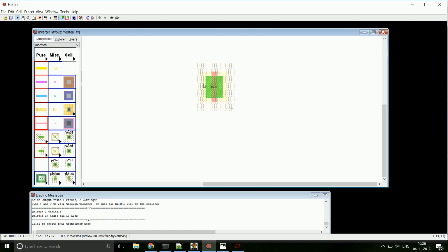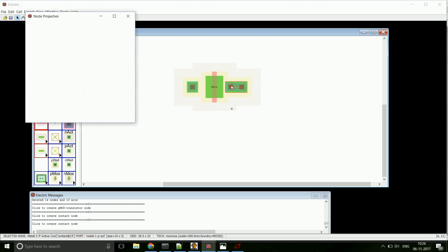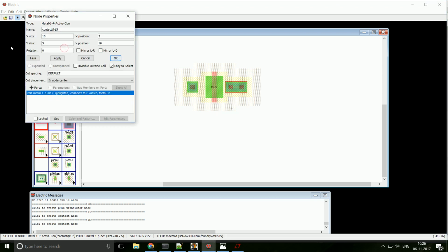So this is the PMOS drain and source regions, and if we need to make a chip out of this, I need to take connections out into the pins. So for that I need active regions, one for the source and one for the drain. So there's P active, take 2. Now size it equal to the PMOS itself, rotate it 90. Done. Similarly this one.